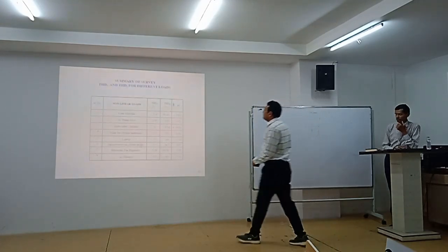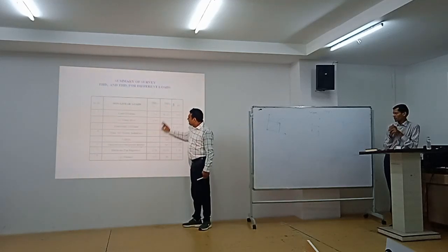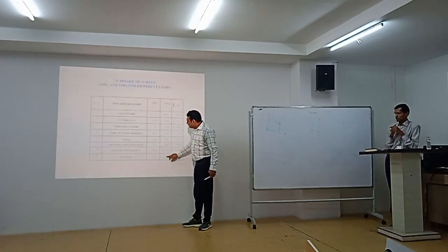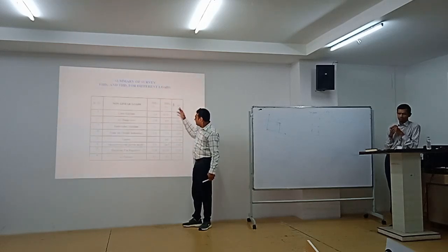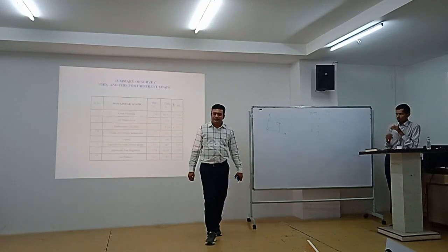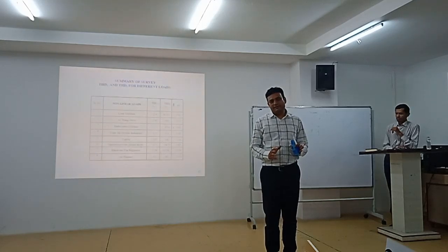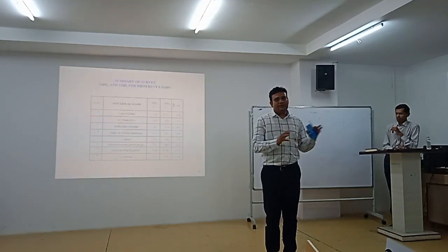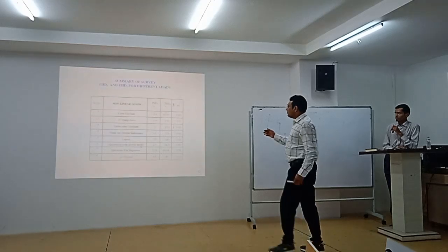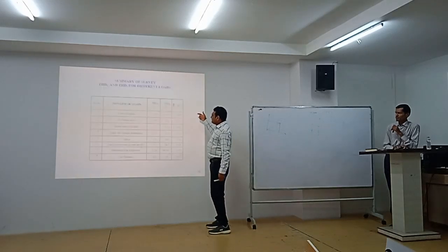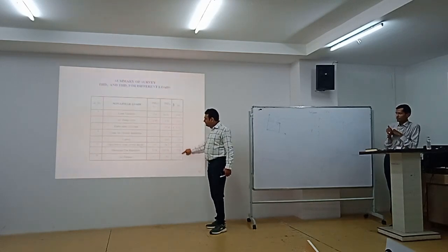So as it is shown, THD voltage is ranging from 0 to 4%, whereas THD current is ranging from 3-5% to something 131%. Right, so current is a major source of harmonics, and along with the IZ drop it makes voltage also distorted. So accordingly, as we have seen, power factor is also going to change.